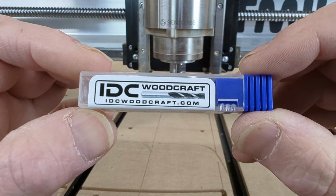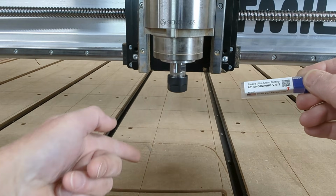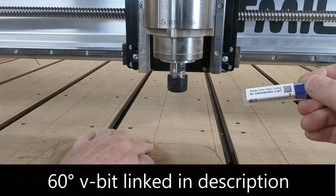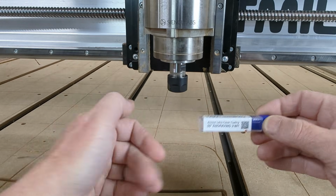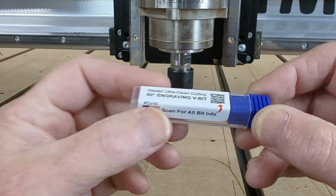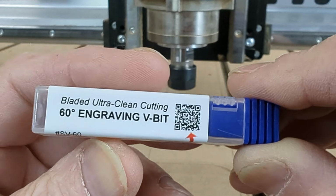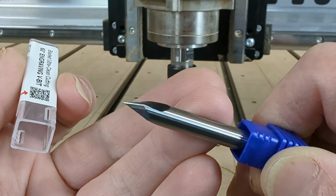I'm going to show you how to set up your machine based on the grid that we just put together in this video. The first thing, of course, is you need to get the right CNC router bit, the 60-degree engraving V-bit. And I like that because I like to get the nice thin lines. You don't want to make these grid lines real wide because then you start to lose your position corner when you're positioning your projects. And so you definitely just want to keep it shallow. This is the bit to use, the IDC Woodcraft Ultra Clean Cutting 60-degree V-bit. That's this guy right here. It is a knife blade style bit.